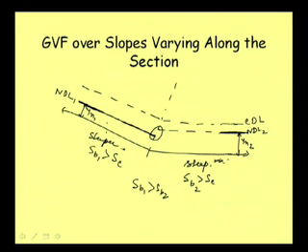And then at a downstream point, it is like that, this depth. So it will have to meet this depth, so it will be gradually rising like this. It is gradually rising from this point, and then it is moving up to this point. And now to name this profile, what we can do, this is our steep slope, so definitely S is coming, and zone wise, in which zone it is, that we need to see.